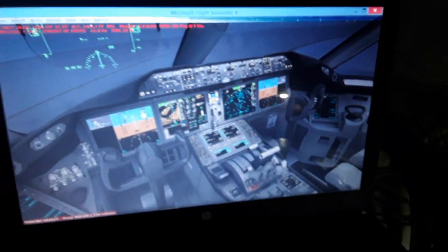You see I'm having here the computer, I'm having the side stick, I also have the mousepad to control, and the keyboard to control the flight management computer, to enter the flight plan of the aircraft and the takeoff gross weight. So we're going to use the takeoff gross weight and other data of the aircraft for this flight. That includes the aircraft plus passenger plus cargo plus fuel on board. The fuel is 30% in the left and right wings, 10% in the center tank.